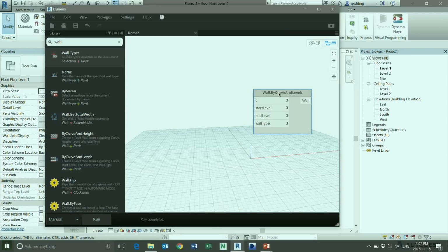Okay. Maybe we should explain why automatic is bad, because in this example that we're giving right now, maybe it's not a bad thing because it's such a light file right now. But when you start pushing a lot of data into the actual graph and it's automatic, if you make one change, the thing will spin, spin, spin, it might even crash. So it's best practice to go with manual as opposed to automatic.